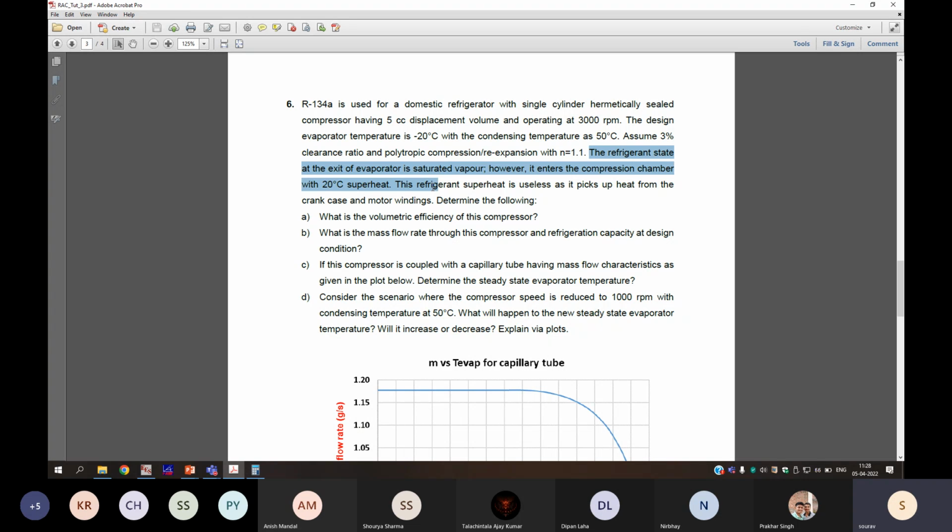When we discussed the mass flow rate drawn in by the compressor, we always have that rho sitting over there, so rho at the suction condition. And in our classroom discussion, we had assumed that the suction to the compressor is exactly the same state as the exit from the evaporator, but it need not be. Because of poor insulation, you can have an LSHX. There could be other reasons: in a hermetically sealed compressor, you have to do the motor cooling by the refrigerant itself.